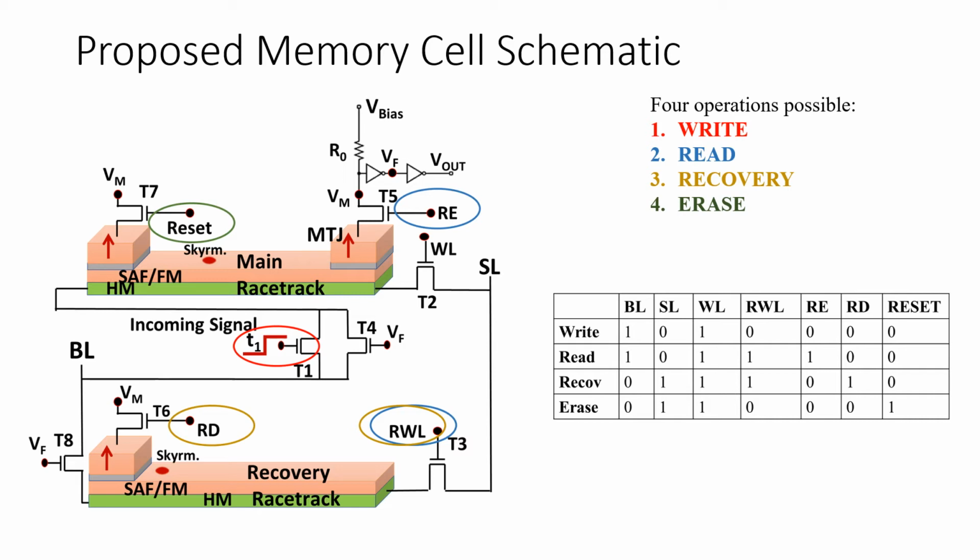I should mention that this temporal information is volatile. That's why you require a recovery. But the skyrmions themselves are non-volatile. They have a certain amount of lifetime. They can last anywhere from nanoseconds, milliseconds, to even years. People have found magnetic bubbles to stay for years. So you can have a different kind of time scale.